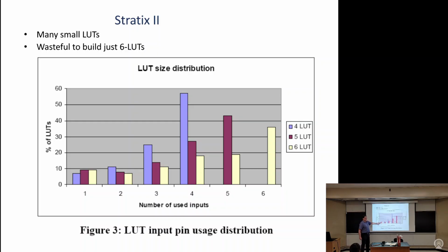So it does look a bit crazy. You do get some NOT gates. This looks super surprising until later in this lecture I'll talk about arithmetic. So sometimes you might have registers feeding each other, like I just got a shift register, so this register to that register. The synthesis tool might put a NOT gate in there. Maybe it doesn't.